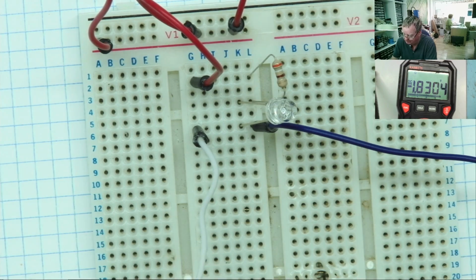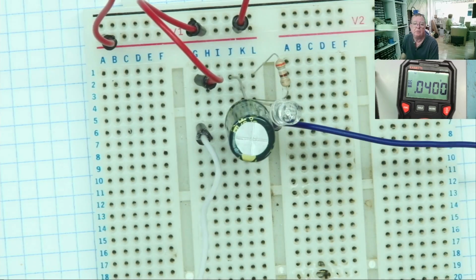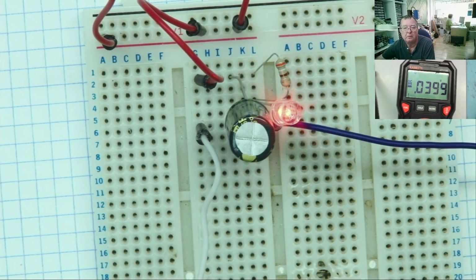Okay, so let's add this capacitor to the circuit, and we'll conduct the same experiment. So we'll put the power on, the LED lights, we'll take the power off. And look at the voltmeter. So what's happening is the capacitor is now discharging into the LED, and gradually the voltage gets too low for the LED to be lit. It goes out. Okay. There. Power back on. Power off. So you can see that a capacitor does in fact store electricity. It's just to get any appreciable difference with an LED, we need quite a large size capacitor.